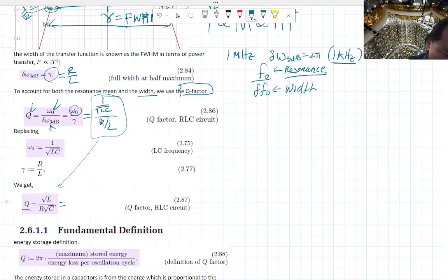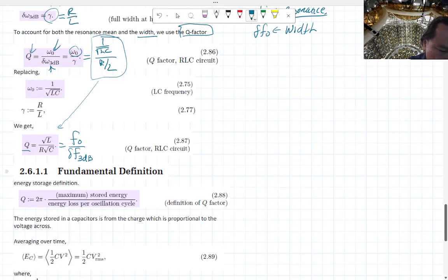If you go in the lab and you try to measure it, you want to measure F3 dB, and then you want to measure the full width half maximum of the negative 3 dB point of the frequency, right? So it converted everything to just frequency, because that's what you'll see in the lab, not omega. It's the same thing, because you just divide by 2 pi the numerator and denominator. Okay, so this is what you'll do in the lab.